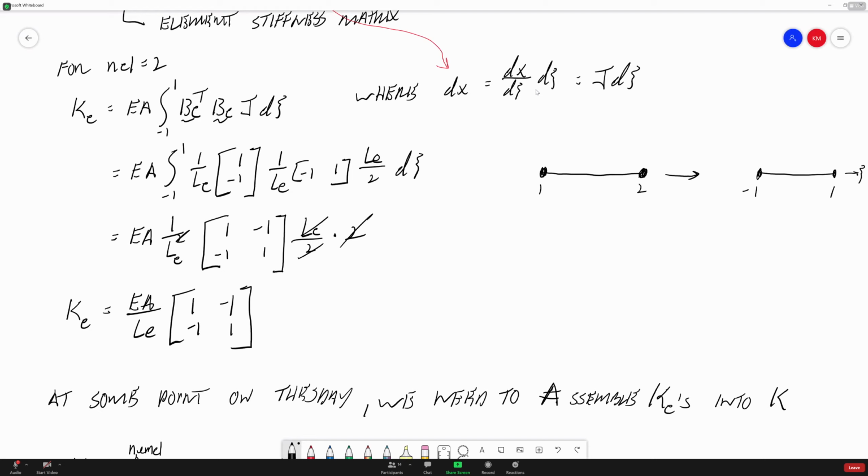So when you're doing ANSYS or Abaqus or whatever, and you have a problem with your Jacobian matrix, it's specific to this isoparametric mapping. There's an issue with that mapping, and it's looking at the derivatives to do that because the Jacobian actually expands to this matrix, and it's a partial derivative.